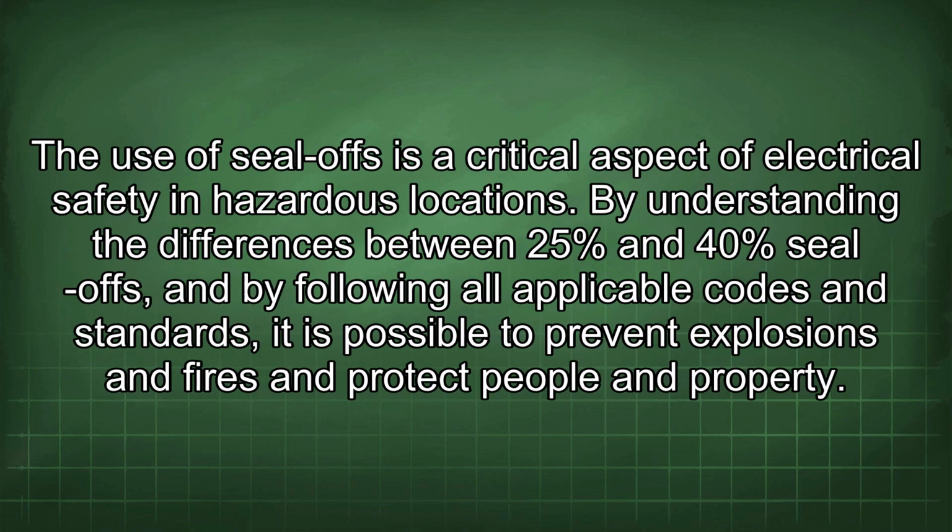The use of seal-offs is a critical aspect of electrical safety in hazardous locations. By understanding the differences between 25% and 40% seal-offs, and by following all applicable codes and standards, it is possible to prevent explosions and fires and protect people and property.